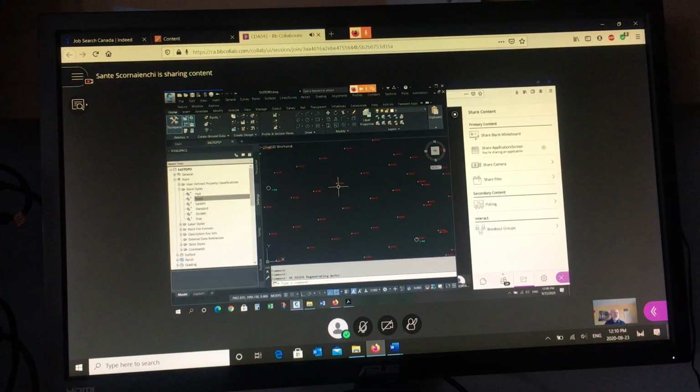Well, there are so many reasons why you might not see something. Maybe the layer is off. Oh, it's on. Well, is it frozen? That's another visibility state. Then you have visibility states, true, false, as well. If there are 10 settings for visibility and one of them is telling you not to see it, you have to know where to find all those settings. And there are many more than just on, off, freeze. It's getting much more complicated, unfortunately.